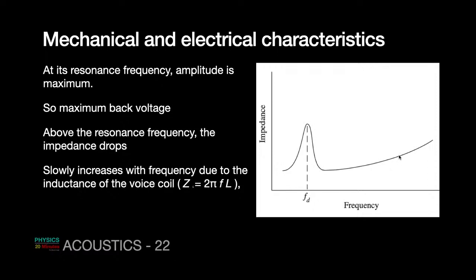Remember, this is representative. In some cases, we have done this experiment over a number of speakers in our laboratory. In some cases, this height is much taller. In some cases, this is much less. Typically, this will increase beyond 15 kilohertz. Most of the speakers are designed to operate not beyond 10, 12 kilohertz. Designing large speakers up to 20 kilohertz is very challenging unless you need a very special purpose.